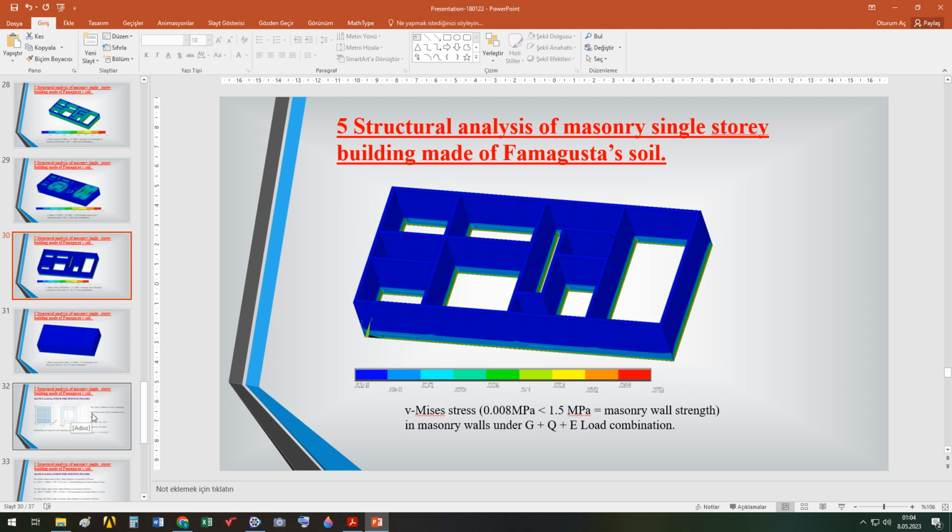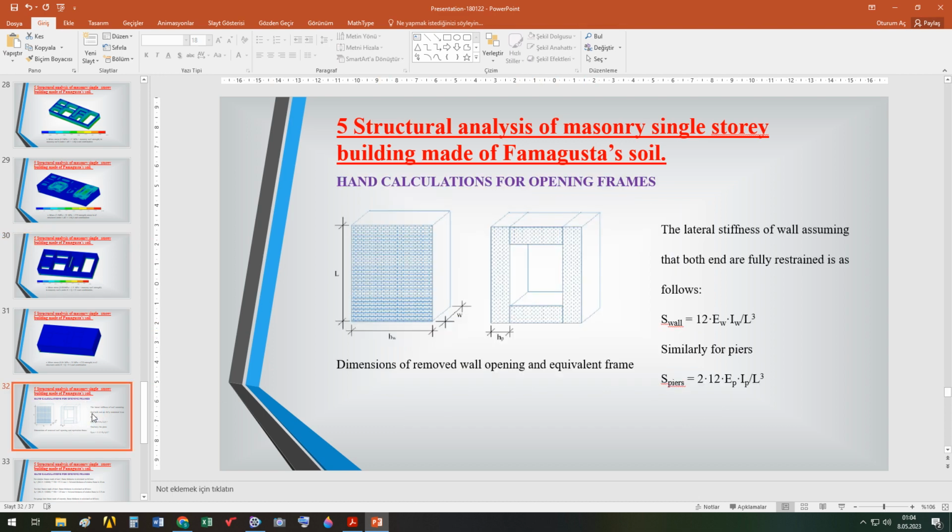So anyway, if I make an opening in the wall, I shall replace something which compensates the lack of stiffness caused by the opening, as a result, for earthquake loads. For example, I did something like that.